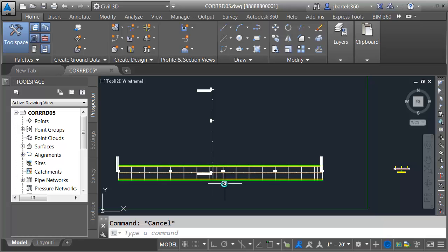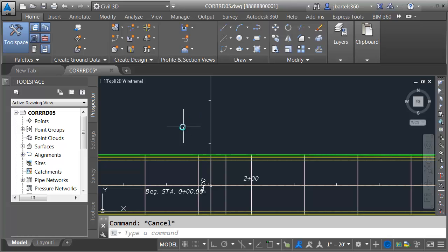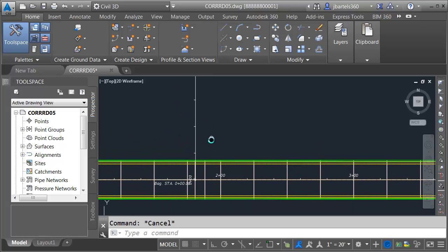We're going to make one other assumption here. I would like both pavement sections for these roads to be the same in width and depth. So we'll keep things simple. It'll give us fewer assemblies. So same assembly for both. Let's talk about curb returns. Let's say I want to do a 25-foot curb return here.